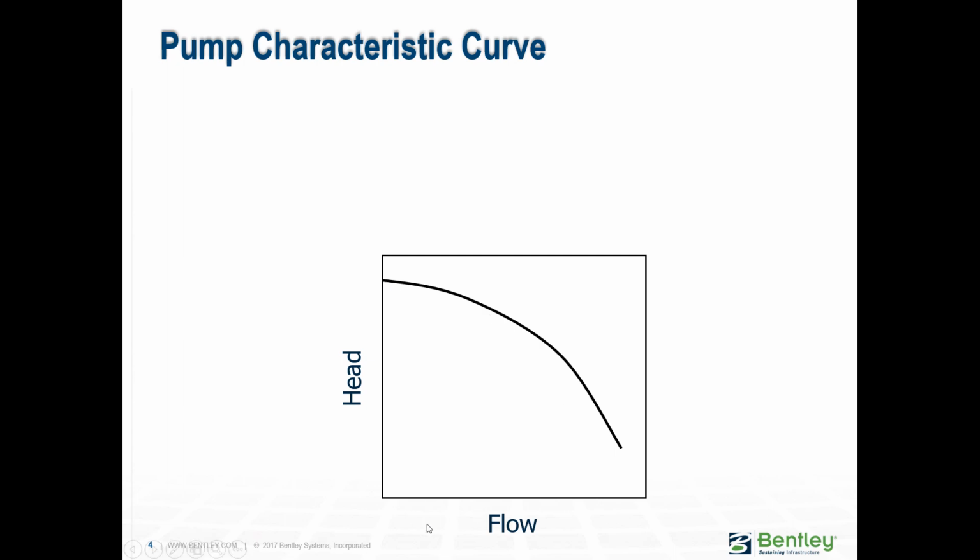And if you look at this, it's flow versus head. So what does that mean? That one pump can operate in different ranges, right? So I'm going to grab my pen, and a pump is typically designed for what we call a design point, typically right around here, which happens to be the most efficient point. But that doesn't mean that it cannot operate in other places like these. It can do that, but it will not be as efficient. And when I speak about efficiency, I mean efficient use of the energy that it is consuming.